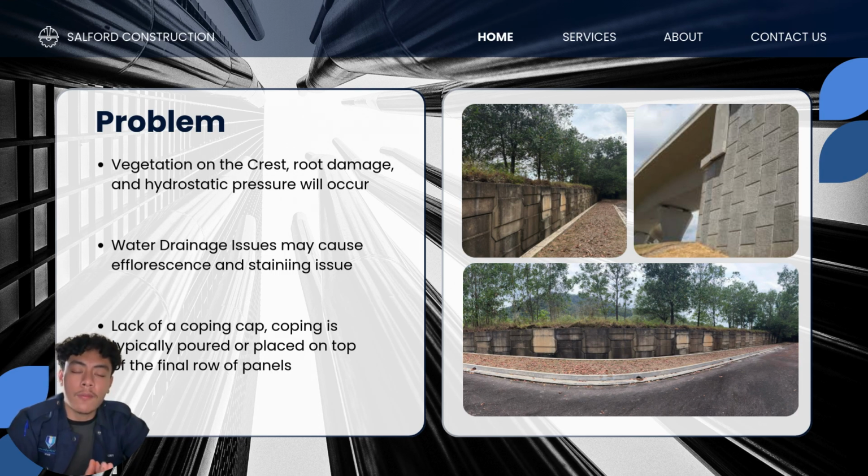And also, we can find the efflorescence. This white chalk on the wall, as we can see, is caused by efflorescence that has built up over time. This happens because the water saturates the concrete or backfill, and the salt dissolves inside of it. So the surface becomes stained as the water evaporates. This is a clear sign that water is trapped inside our wall or overflowing through it excessively, which can eventually corrode the steel reinforcement or wash out the soil particles.